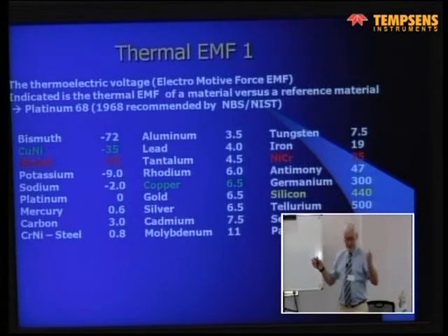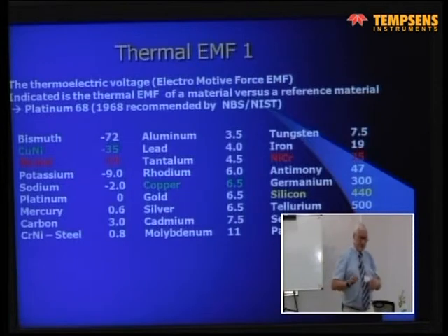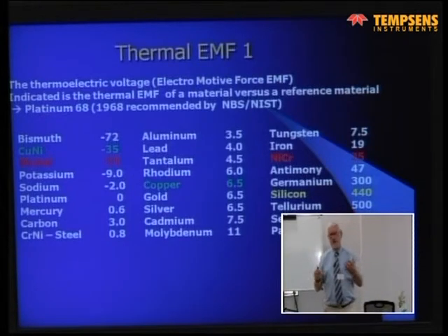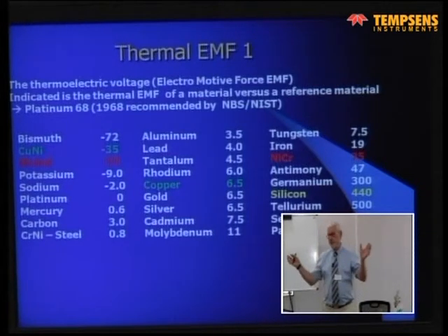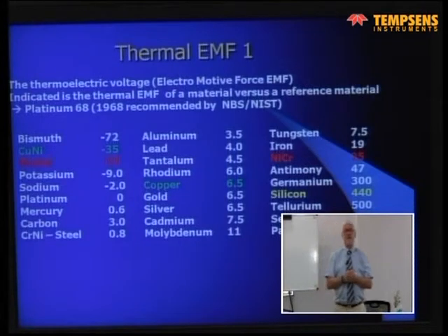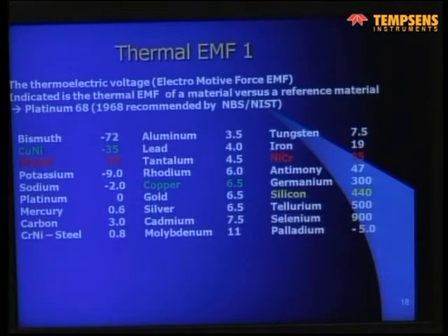Everything contains silicon in some kind. So when you handle bare noble metal wires, you have to do it in a clean ambient, with protective gloves, in a dust-free atmosphere, and so on. It's essential. And when you put it in an industrial environment, you must carefully look at the environment and protect the thermocouple from influences, especially from silicon.